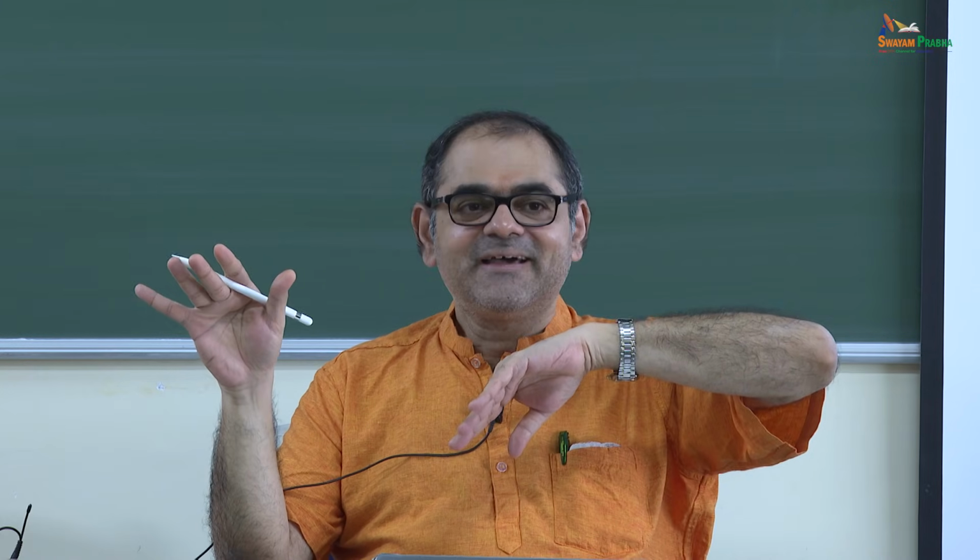So all I want to say is the following thing. Forget all that. Okay, it's impossible to explain this without a nice animated picture. But I want to say the following thing. What I want to say is that no matter how it touches, at every point there is no tangential component of the action. So there is zero friction. So it is the ideal gearing profile. The involute of a circle is the ideal gearing profile.